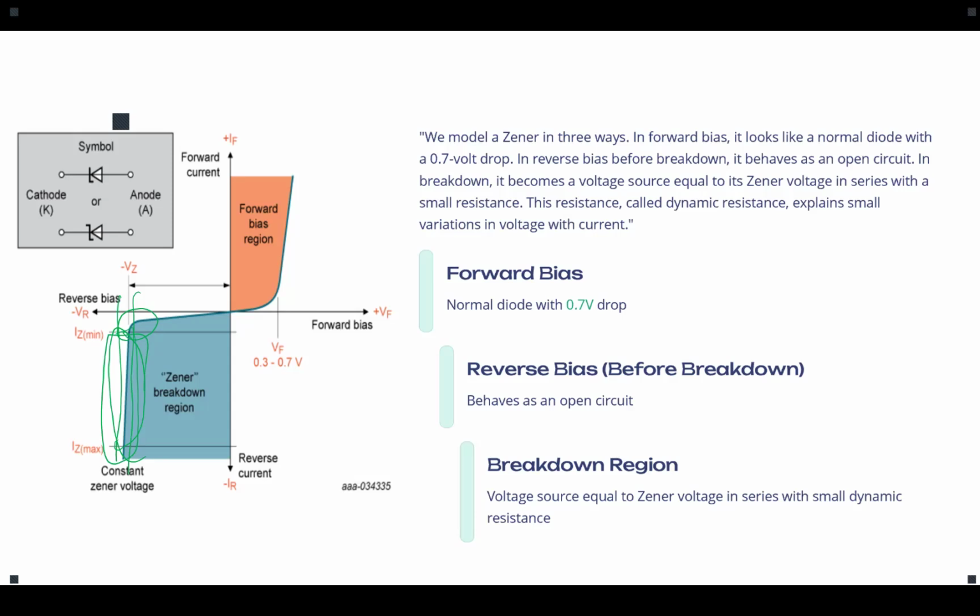We have different types of Zener diode. There are Zener diodes where the Zener voltage is like 4.7 volts, or some where the Zener voltage on that model is like 5.1 volts. Different diodes would stabilize, would regulate the voltage across the diode when they are in reverse bias at the specified value for that model. Is the statement clear for everyone? Any question?